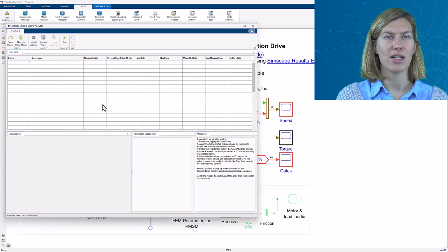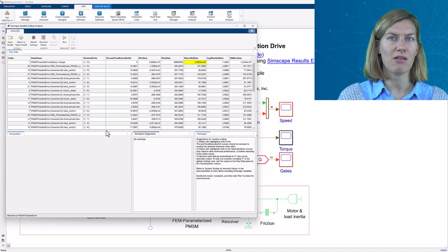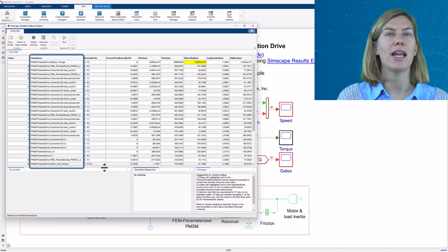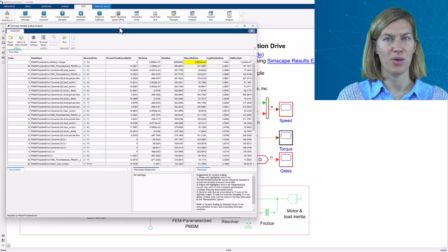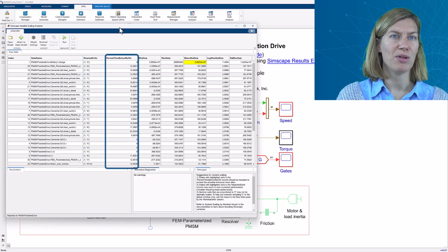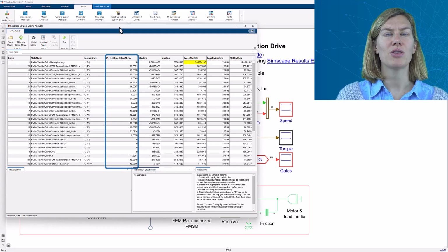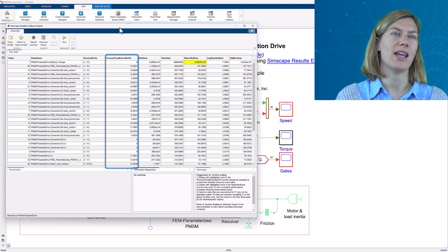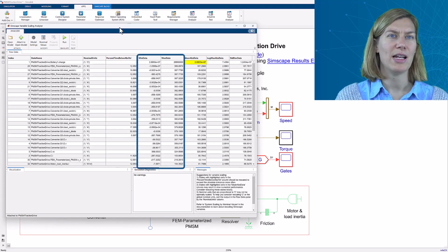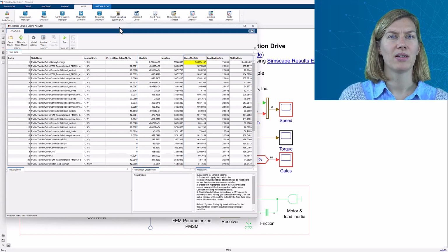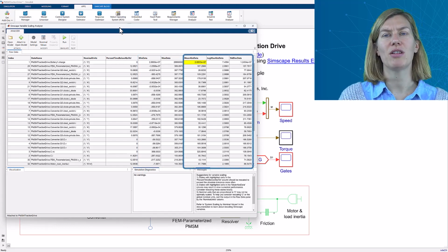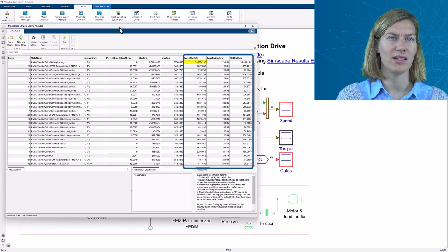The results in the raw data pane display a table with an index number representing a retained state, the state name, and the nominal value unit pair associated with it. The percent time below absolute tolerance column refers to the percentage of the simulation time that this variable has a value below that of the absolute tolerance parameter. This applies when the auto-scale absolute tolerance setting is disabled. The min data and max data are minimal and maximal values during the simulation run for the given variable. And the remaining columns give additional information on variable statistics, such as their time-weighted statistical mean.